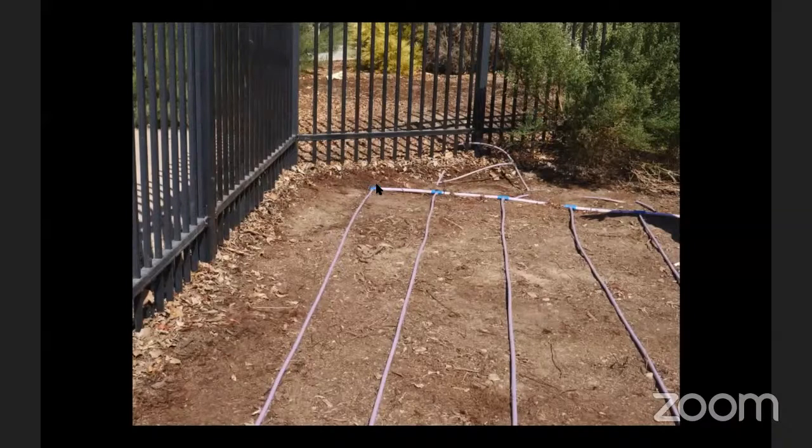And then down at the far side, so that everything reconnects nice and evenly, it is a best practice to do what's called an exhaust header, where you use that larger pipe again and the fittings and adapters again, so that when the water gets to the end, it can kind of evenly move around, and the water speed where this is all potentially coming together and then going back through the individual lines through the larger pipe is lower. It's not the end of the world if you don't do that in most residential size systems, but it really is the best practice.